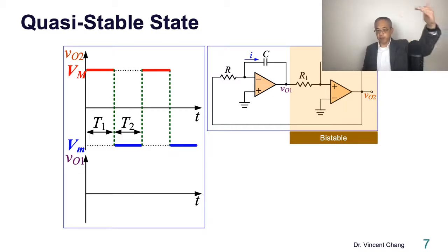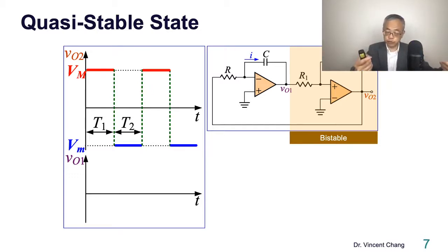So when you send a square waveform into an integrator, what would you see? A triangular wave, right? Because when you send a constant high into an integrator, the output becomes linear, first order. Because it's inverting, is the linear going to go up or go down?